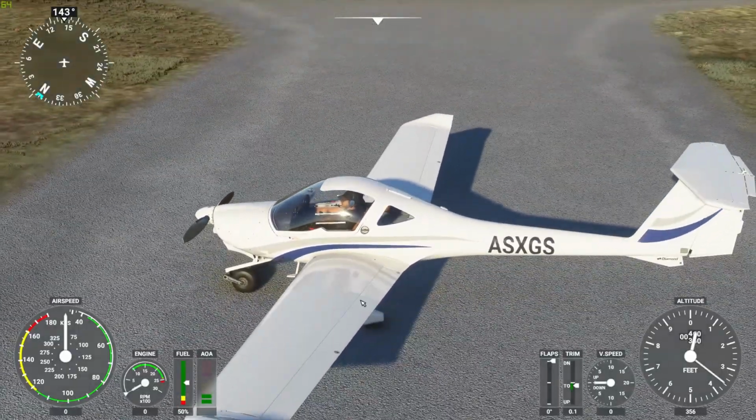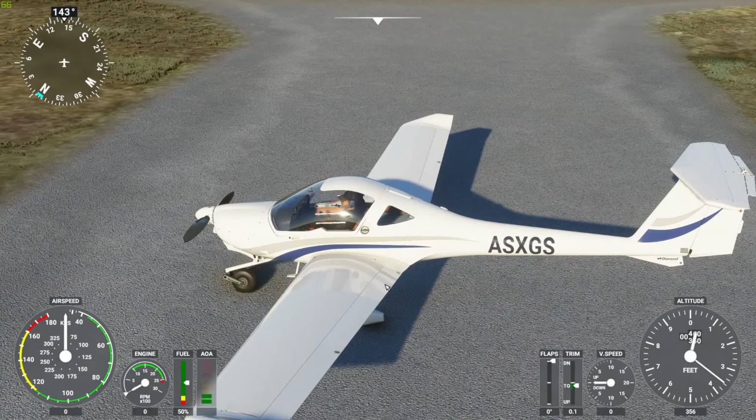So flaps are in the inboard section here, covering looks like about 2/3 of the wing, and the ailerons are covering the final third of the wing. And interestingly, we get this little bit of fence. If you look in the other wing there, we can see that there's a protrusion of the aileron up into the slipstream there. So that's some mass balance, which will help prevent flutter and also improve our aileron control.